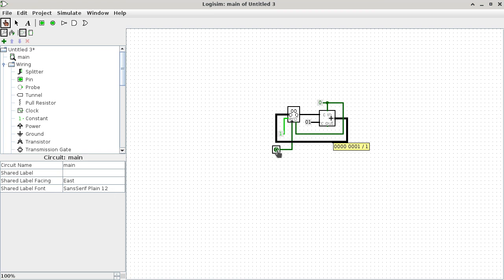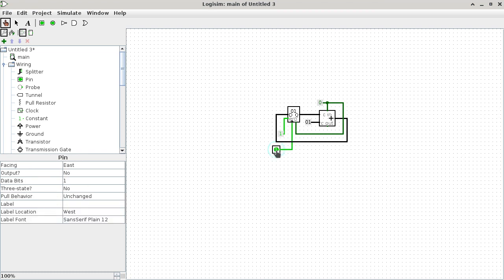Okay? So let's go ahead and change this from a 0 to a 1. You go like, okay, I was kind of expecting the register to go crazy to 0, 1, 0, 2 all the way. Why is it stuck at 0, 1? Exactly, because the clock is now at a constant of 1, which is not a rising edge, right?